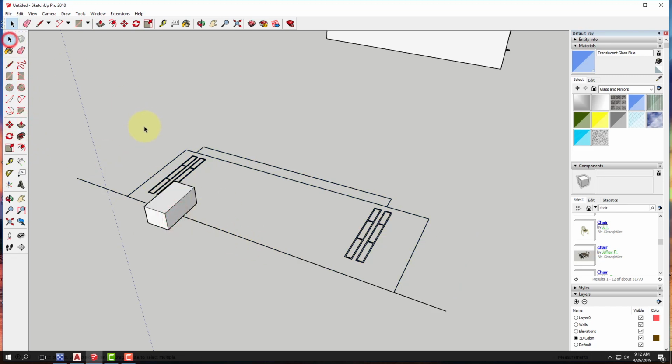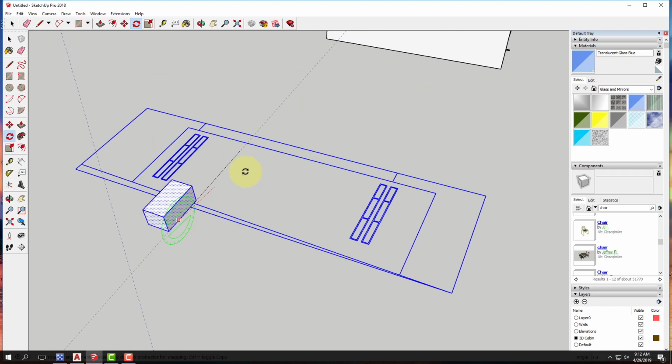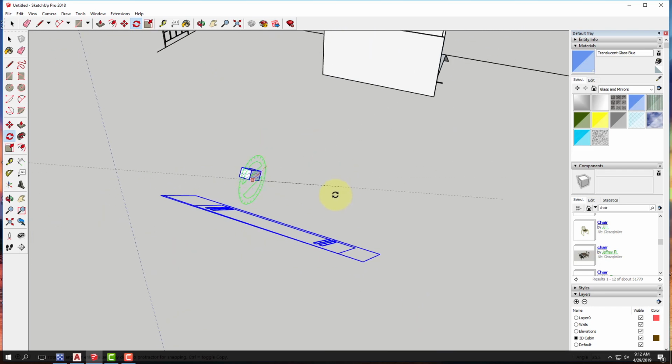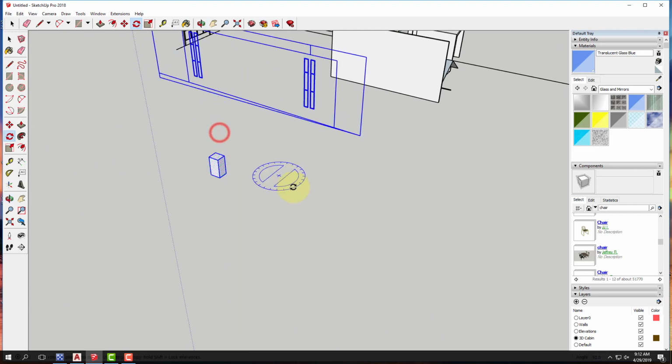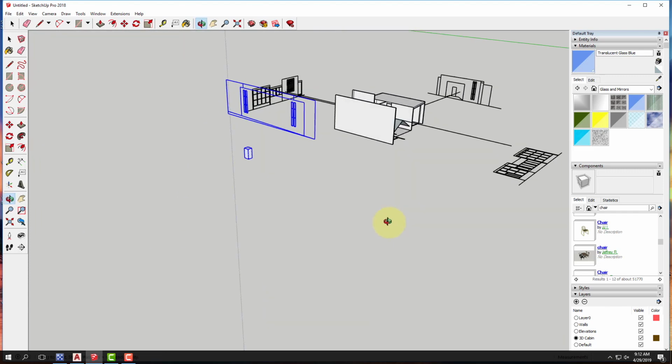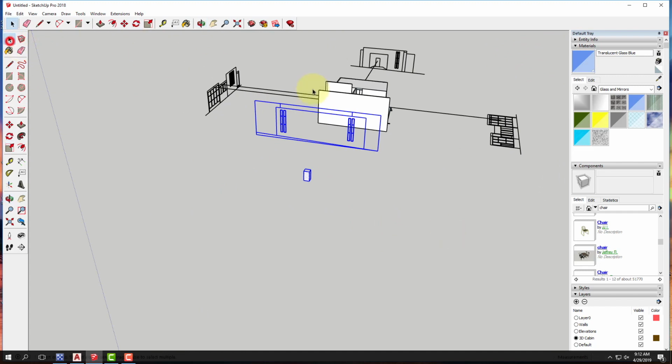And once you have that, then it's pretty easy to select both there. When you go into rotate, the protractor will stand up on edge for you. And so then it's just a matter of starting with your drawing and then rotating it up. It looks like my box was floating in relation to where I did it, so I have some height corrections to make. But essentially that gets you up into that plane. And then it's just a matter of adjusting for your height.